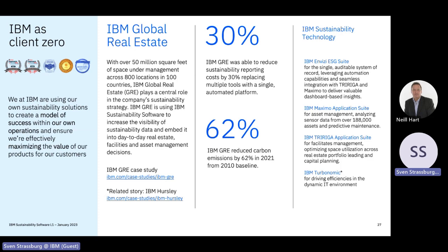So our approach is to say, how do I run the machines hotter? How do I run them more dense? So 75% capacity at 85%. So instead of them running at a nice 21 degrees, 25 degrees cold air in, 38 degrees hot air out, how do I actually close the entire mechanical air handling, air cooling side down and go to natural cooling? So that's the sort of thing that we're doing.